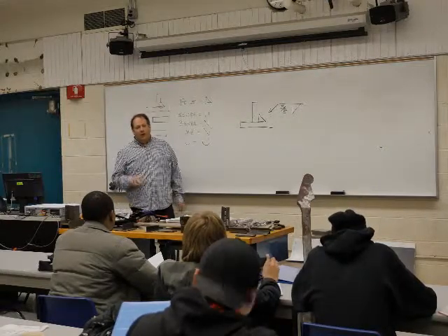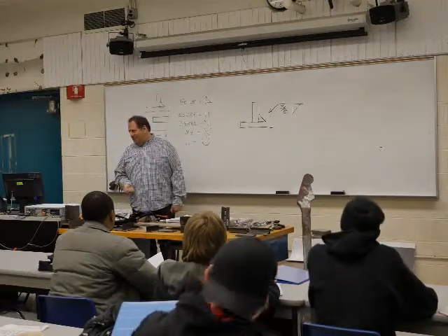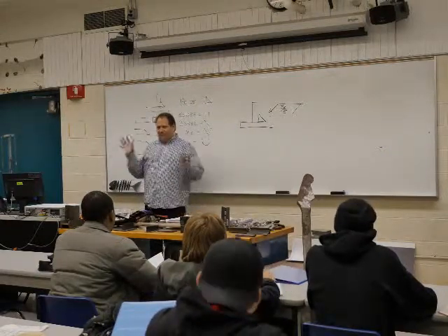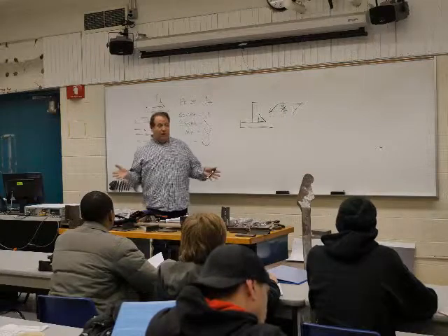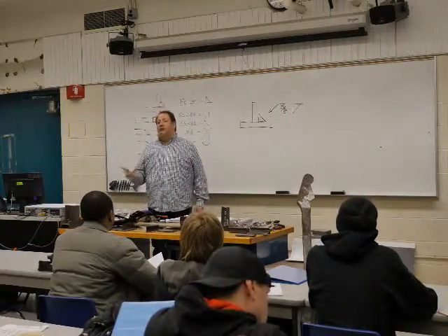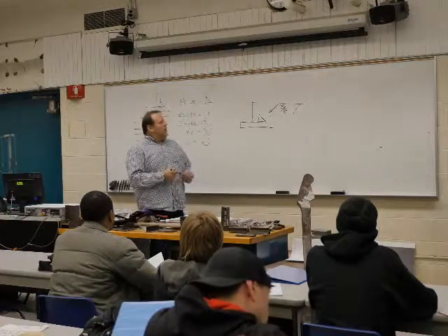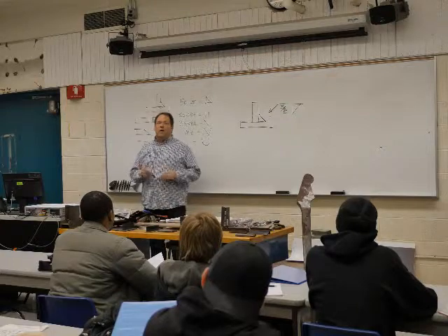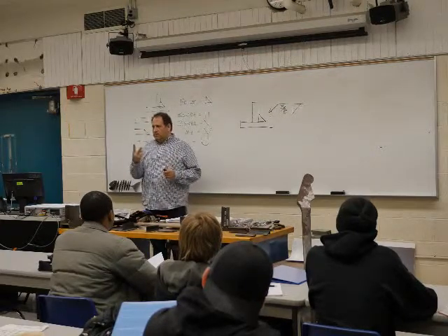First, that's the face of the weld. That is not it, actually, because that's what a lot of people assume. Not that that's a bad answer, because when you're looking at the weld, that's physically what you're looking at. But that's not the size of the weld. How many legs do we have? We have 2 legs. And welds have 2 legs. Okay?